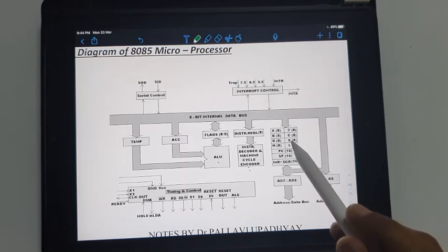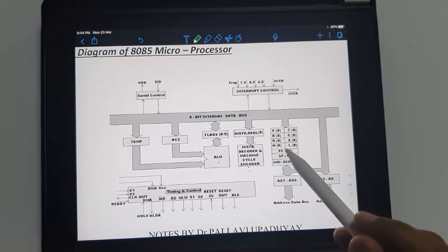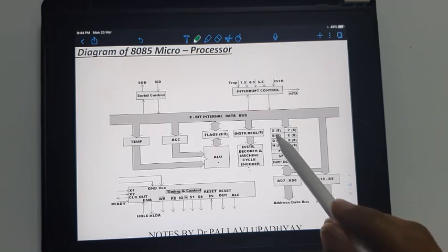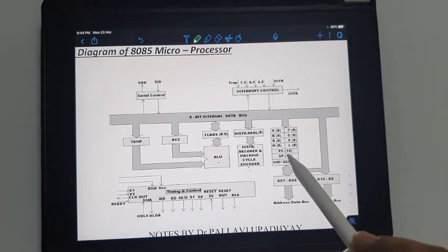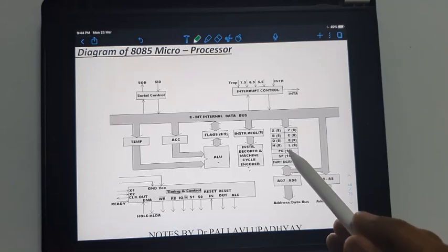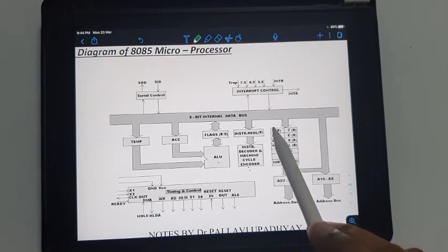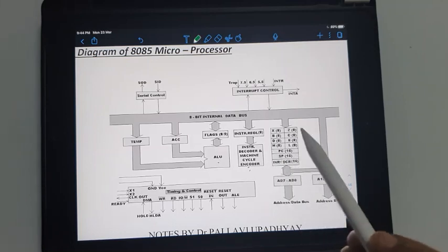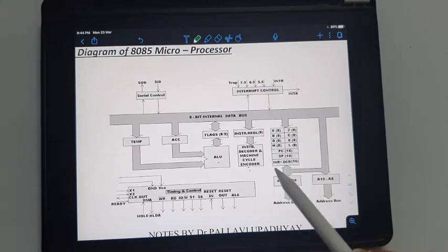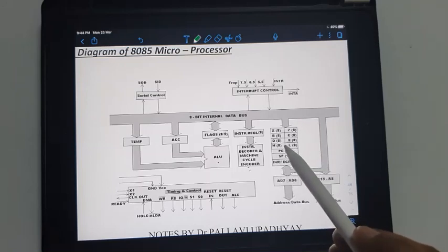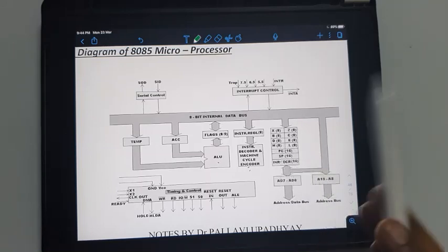Meaning if my program is being executed and the microprocessor is executing instruction number 10, so instruction number 10 will be brought into the instruction register. At that time, PC will be storing the next instruction. That is, maybe PC will be storing 11, because what instruction has just been fetched into the instruction register? The instruction that was on location number 10. So now PC will be holding the value of the next instruction to be fetched by the microprocessor. That would be 11. Okay, we'll study this in detail.